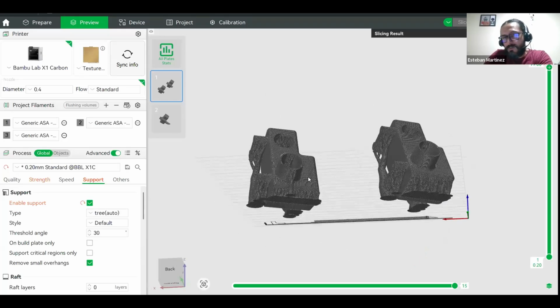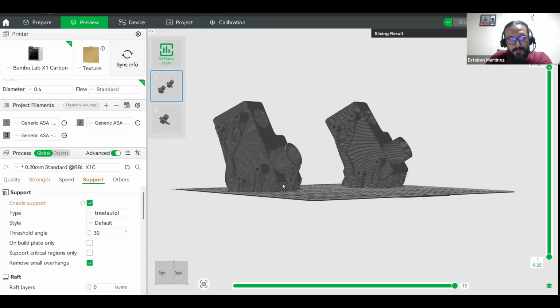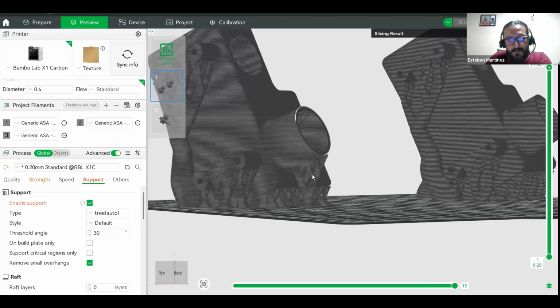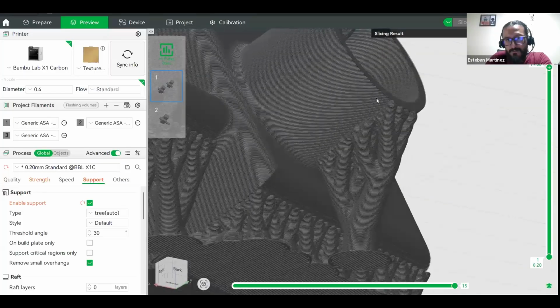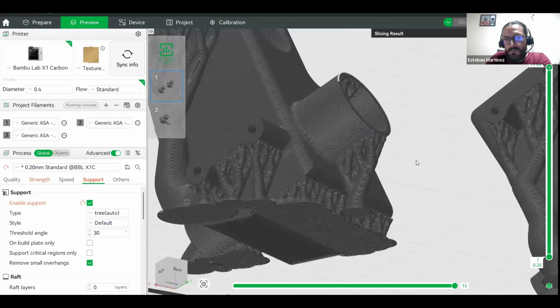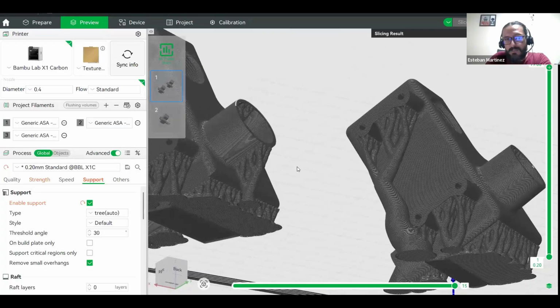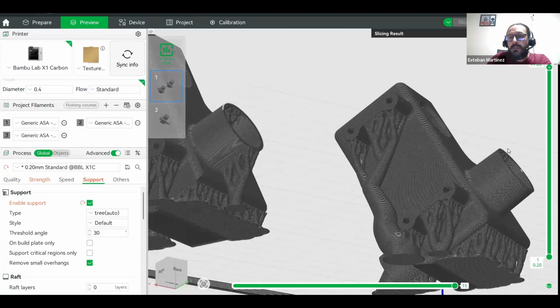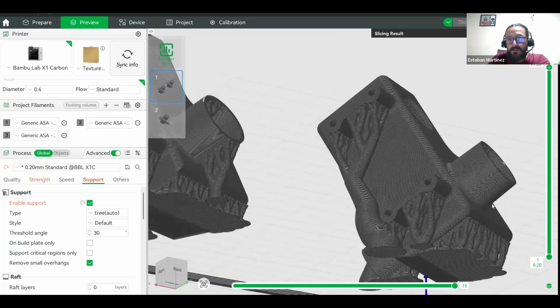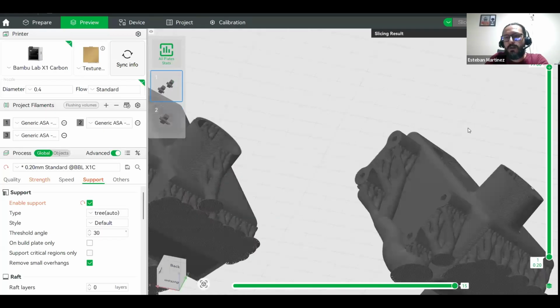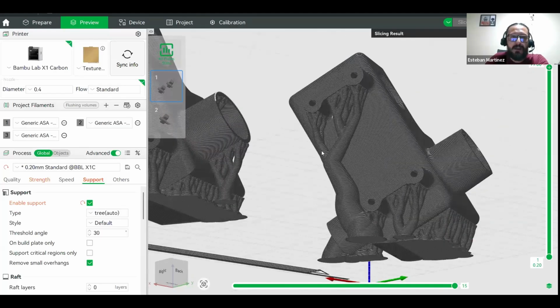So I used tree support type. It simply jammed the entire thing. So the bad surface finishing is coming from this type of support, but as we can see, also with 30 degrees, we are not going to have supports for this inlet. So that's something that calls attention, to say, okay, let's persist with the one with 30 degrees instead of 25.